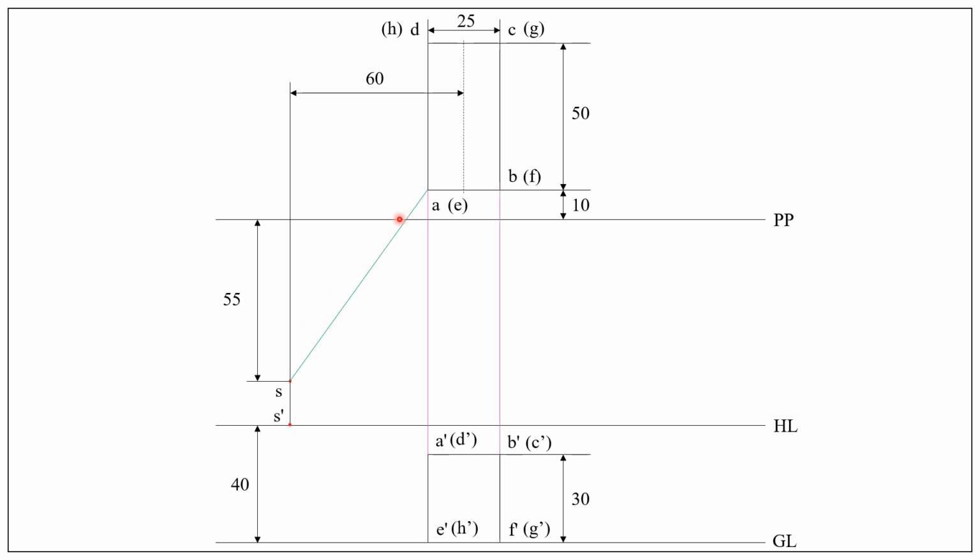This line or the visual ray intersects the picture plane at a point and name that point as A1, E1, because in the top view this corner represents both points A and E. Therefore, the visual ray which pierces the picture plane is named as A1, E1.